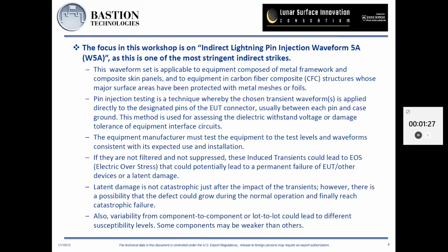The focus in this workshop, as I mentioned, is waveform 5A. The reason I'm focusing on this one is that it is one of the most stringent indirect strikes. This waveform is applicable to equipment composed of a metal framework and also, for example, carbon fiber composite structure, which is not a good conductor, so the conductivity is very low with this type of structure.